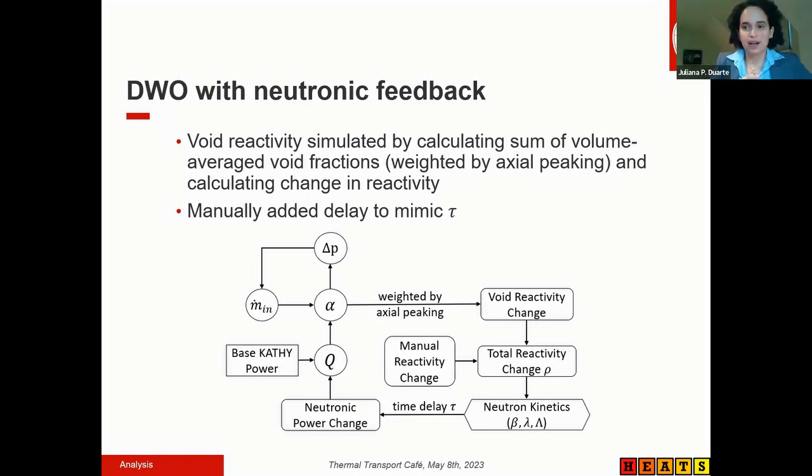It is fixed in the experiments, since the shape of the power is given by the thickness of the cladding that has been used in the experiments, while in the actual reactor, the shape of the power is going to change, depending on the void fraction along a channel and several other reactor physics properties of your fuel. Another large difference is that during the experiment, they kept the average power of the bundle constant and only allowed the oscillations of the power to fluctuate around this average power.